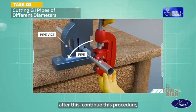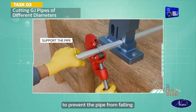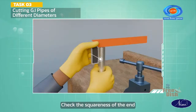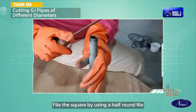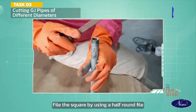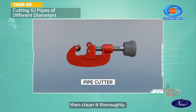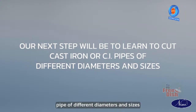Continue this procedure. Support the pipe with the free hand to prevent the pipe from falling. Continue this procedure until the pipe is cut. Check the squareness of the end using a tri-square. File the square by using a half round file. Check the condition of the cutter. Then clean it thoroughly. Our next step will be to learn to cut a cast iron or CI pipe of different diameters and sizes.